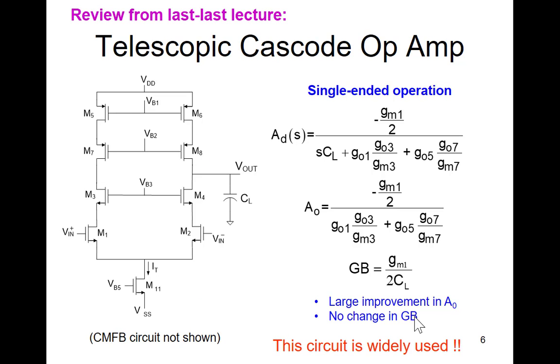And of course here were the gain expressions. And how long did it take us to get those gain expressions? We wrote them down by inspection, didn't we? Once we had that Cascode circuit analyzed, we wrote down the gain expression for the telescopic cascode amplifier by inspection. We didn't call it a telescopic cascode amplifier. This is just really the Cascode circuit converted into an operational amplifier, and then we named it the Cascode configuration, or the telescopic cascode configuration.